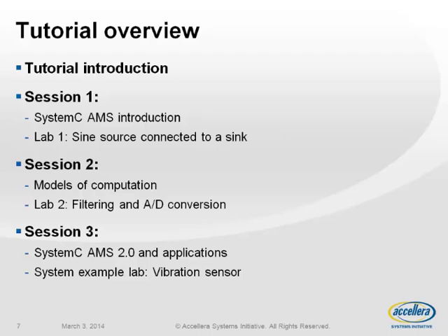The second session, we dive into different models of computation. So we will look at AC domain, we look at signal flow domain and electrical domain. And the lab there is that we are going to extend that simple example, doing some analog filtering, and we are going to introduce a sigma delta ADC. And then session 3 is the more advanced stuff. So we are going to look at the extensions introduced in SystemC AMS 2.0. And as a bit of a system example, we will look at a vibration sensor.